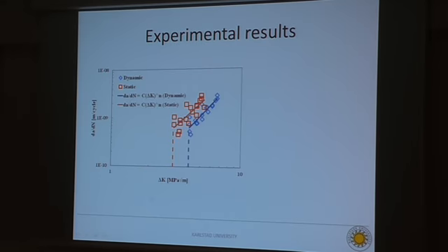The experimental results I'm showing here are the results from both dynamic and static cracks. This is the crack growth rate, da/dN versus delta K, where we're trying to fit to the Paris law, and the result from the dynamic calculations. You can see that n is equal to 2.86, and the threshold value is around 4.1.